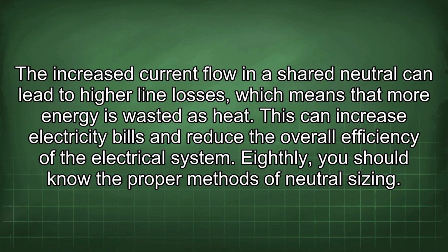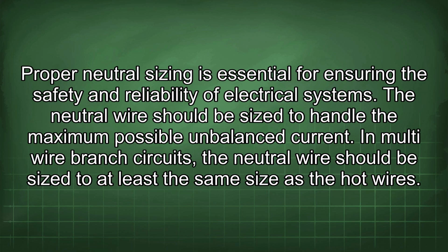Eighthly, you should know the proper methods of neutral sizing. Proper neutral sizing is essential for ensuring the safety and reliability of electrical systems. The neutral wire should be sized to handle the maximum possible unbalanced current. In multi-wire branch circuits, the neutral wire should be sized to at least the same size as the hot wires.